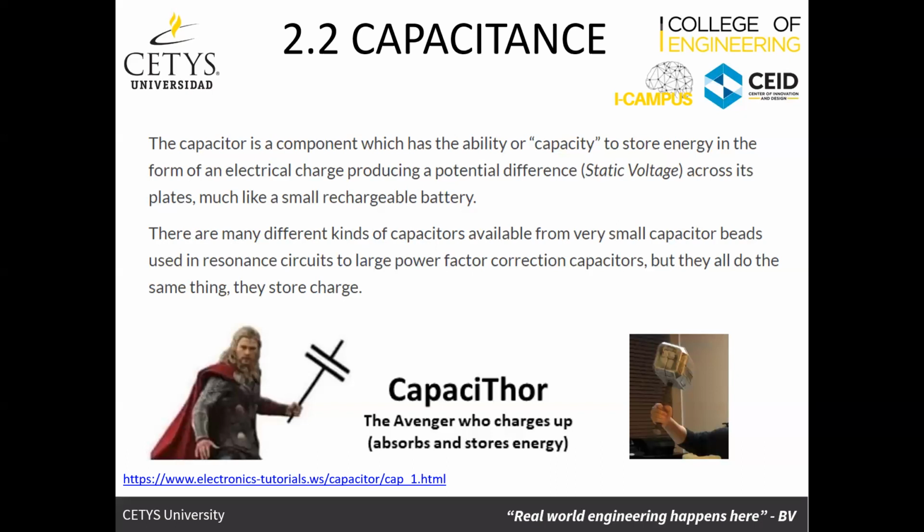However, the capacitors have the energy stored. So if you start working on it and suddenly touch something, the capacitor is going to discharge on you. That's why servicing electrical equipment, even though it's disconnected, could be dangerous. For example, if I'm cleaning an electrical device, like an appliance in the kitchen, on the outside. Yeah.